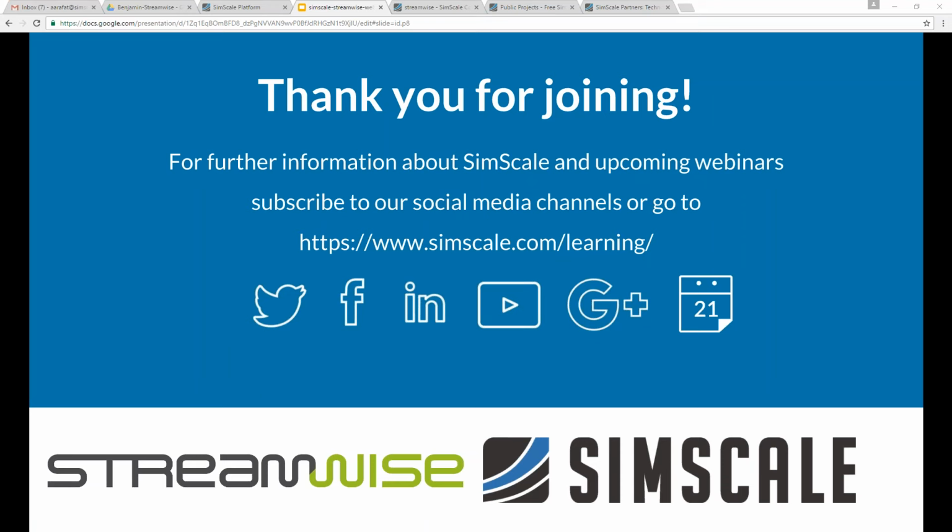It seems to be more related to the numerical simulation of the Ahmed body. This is placed by Marco, and he asks, why are there only 2 to 3 boundary layers on the Ahmed body? I have read some manuals saying that for a turbulent flow, at least 8 to 20 layers are necessary. Yes, in fact, it's recommended that to better capture the boundary layer, you should have at least about 7 or 8 layers. For this demo project, we did not have so many, just to keep the project size low so that users can easily copy it.